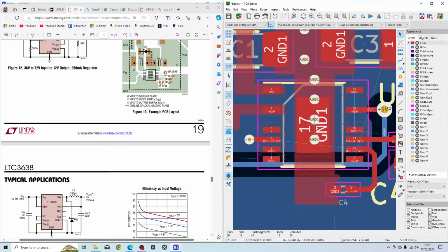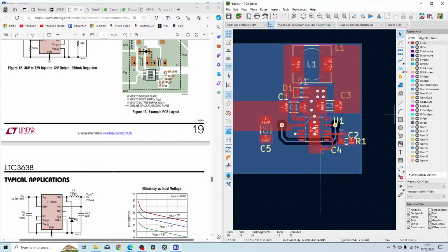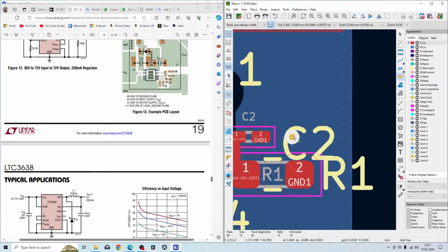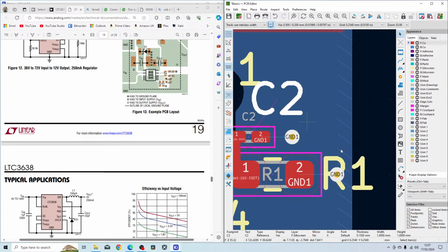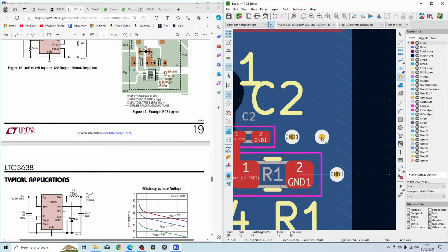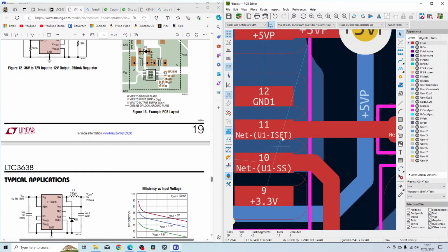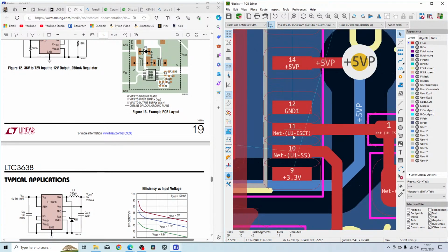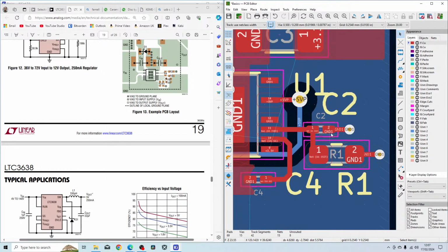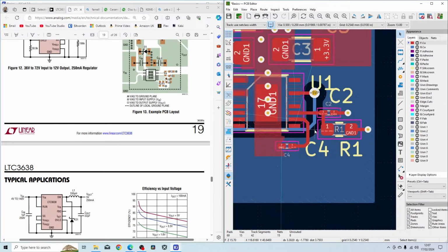So nice solid connection to the ground plane on the other side. And basically do the same thing for this. Move this out here, move this out here, and I don't think that needs anything, that's not going to be anything too demanding. Obviously I would make sure that there's no high frequency components going from that track. If there was, I would make sure that we have multiple wires to reduce inductances and things like that.